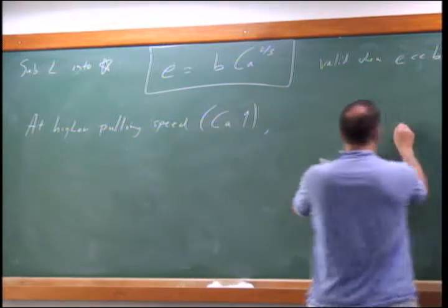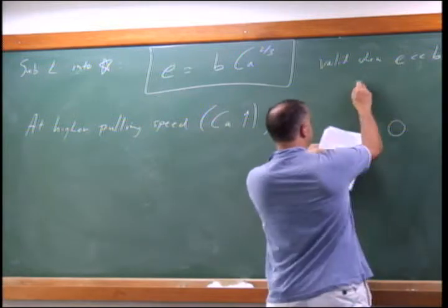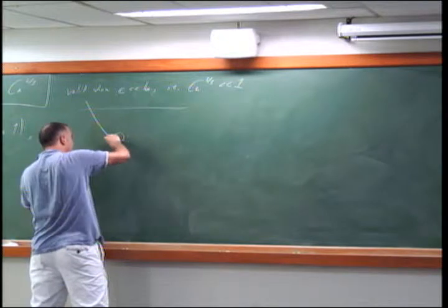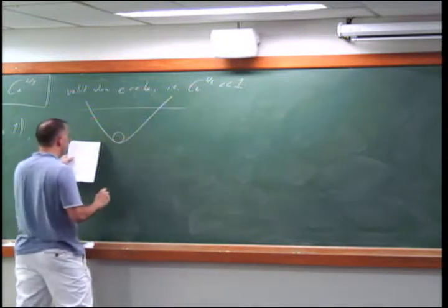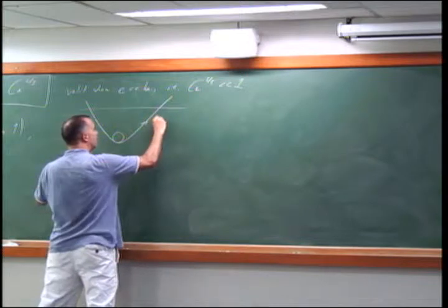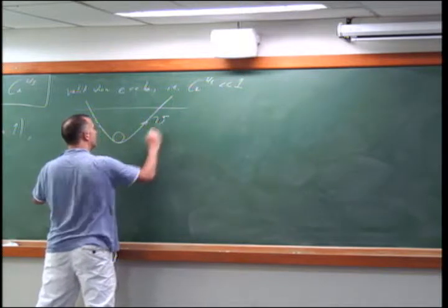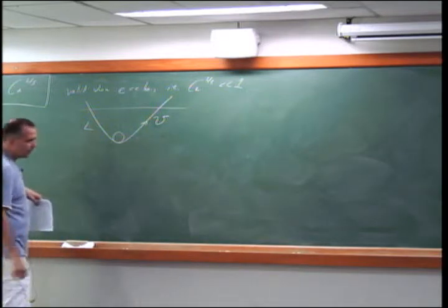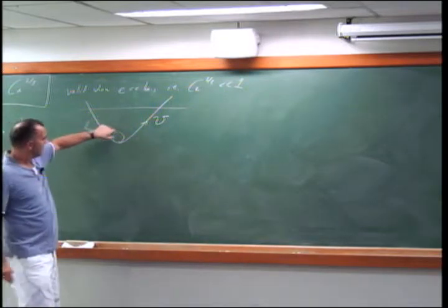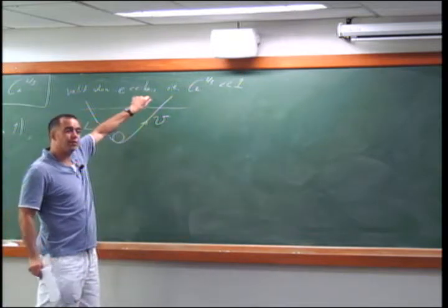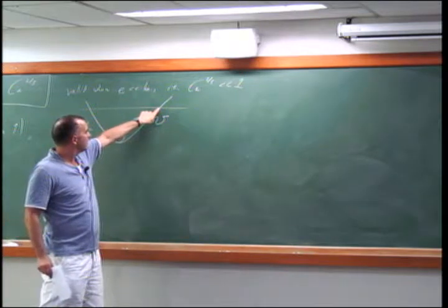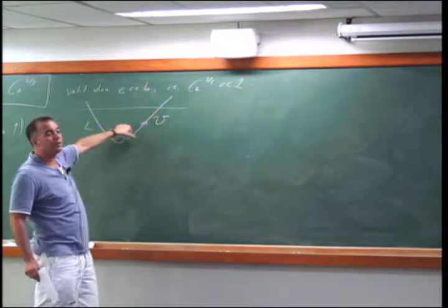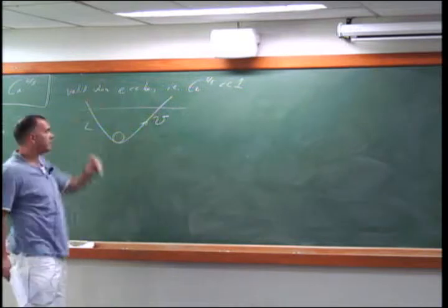You basically have a bath, and you have a fiber going in around some spindle, so it's being pulled at high speed. And in the viscous limit, basically what happens is you simply entrain fluid as you move through the fluid. Okay? So it's not determined by the local dynamics. You basically entrain fluid as you go through and you get this big, thick layer coming out.